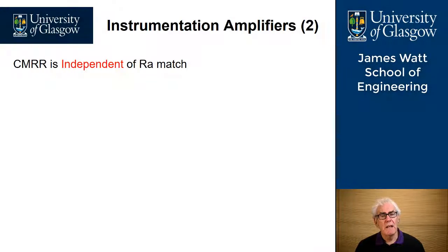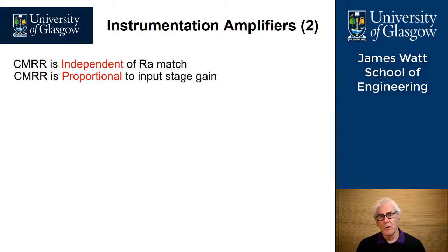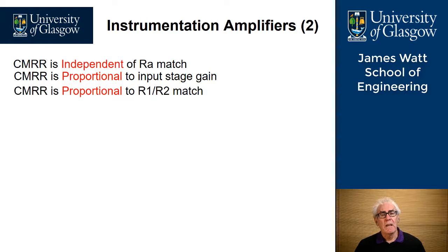We've looked at instrumentation amplifiers, and we've proven that common mode rejection ratio is independent of RA match. We've also proven that common mode rejection ratio is proportional to the input stage gain of an instrumentation amplifier. And finally, the common mode rejection ratio is proportional to the R1, R2 match in the difference amplifier if we actually put gain in the difference amplifier.